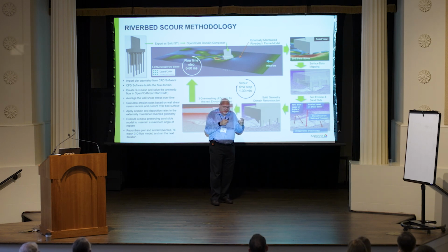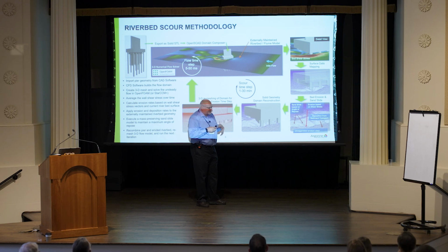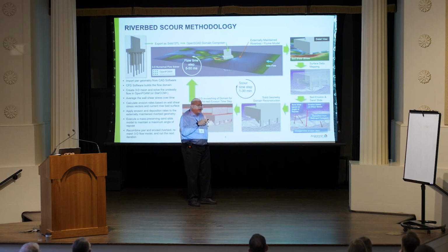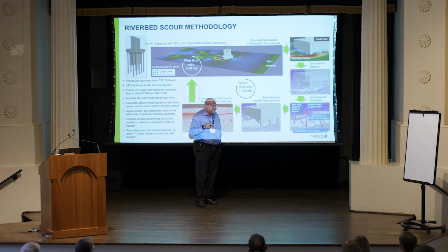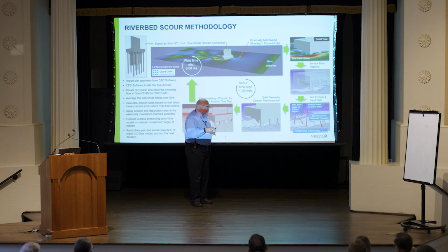And then once the material gets into the flow in the CFD calculation, it moves along as a dispersed phase within the flow field. So it's a multi-phase calculation where you can have discrete particles represented as a fraction of volume in the cells, right? And then once the material experiences flow conditions where it starts to build up, we know that that is where it has to deposit it. That's the most difficult piece to explain because we have to go deep into theory with divergence and things like that, right? But we have a way to tell where the material falls out onto the bed again, right?